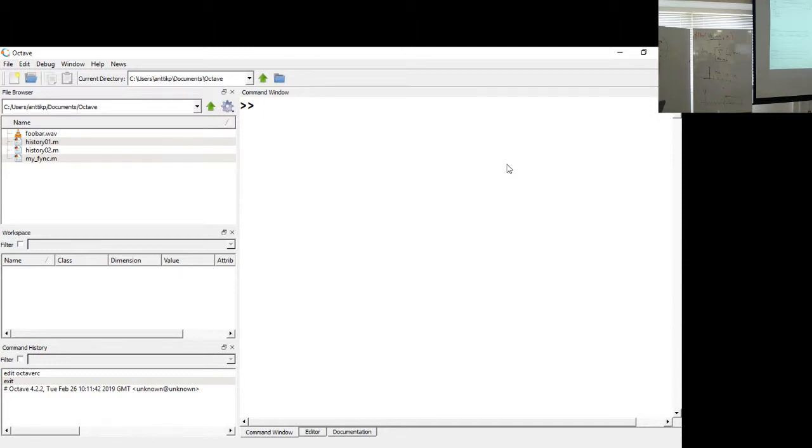Okay, so 0.5 and that's 0.5. That's minus 0.5. So this is the imaginary axis. This is the real axis there. And then that, okay, this angle here is 250 hertz angle. Good. Yeah, 250, 500, 750, 1K. And actually back to here it's 2K. So full circle is the same as sampling rate. Okay, good.